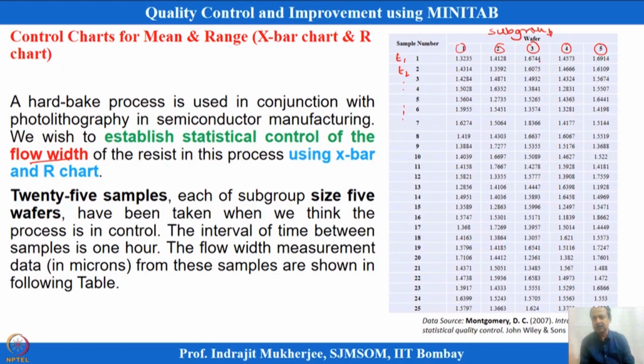Precaution has to be taken when we decide the subgroup size. Variability within the subgroups should be minimum, and between subgroups should be maximized. Cost also has to be considered, because the more samples, the costlier it is to measure.